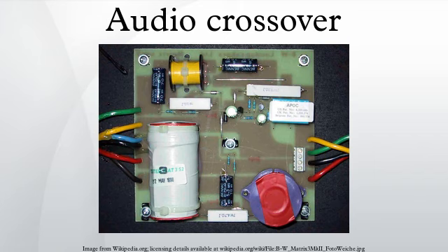In the latter case, the final acoustic slope is usually steeper than that of the electrical filters used. A third or fourth order acoustic crossover often has just a second order electrical filter. This requires that speaker drivers be well behaved a considerable way from the nominal crossover frequency, and further that the high-frequency driver be able to survive a considerable input in a frequency range below its crossover point. This is difficult in actual practice. In the discussion below, the characteristics of the electrical filter order is discussed, followed by a discussion of crossovers having that acoustic slope and their advantages or disadvantages.